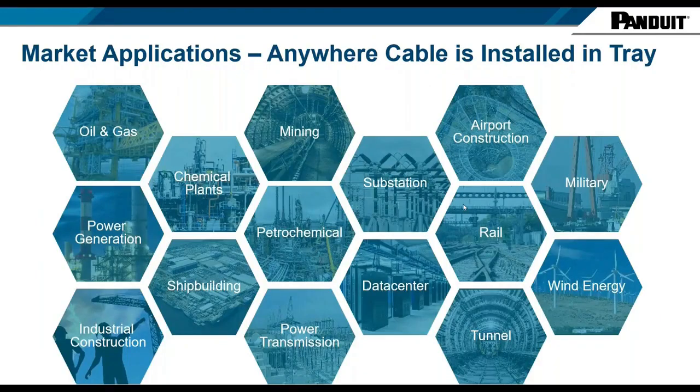And where do we use cable cleats? Well, wherever you have a power cable with a fault potential, doesn't matter what vertical, any of these verticals, you have power cable, you also need cable cleats for that power cable.